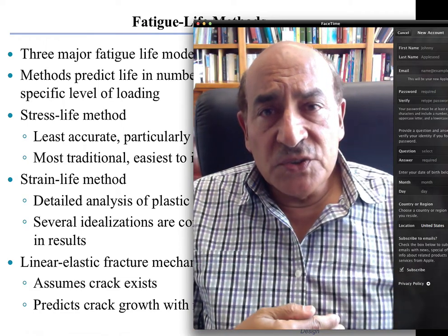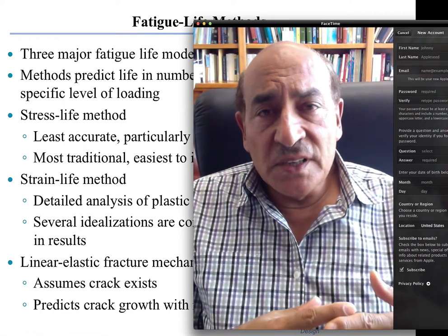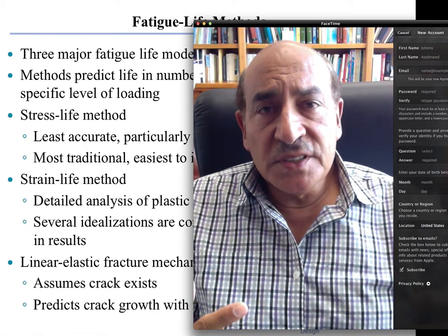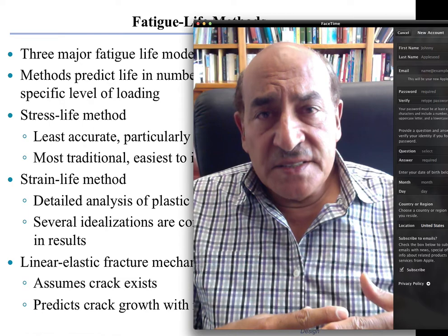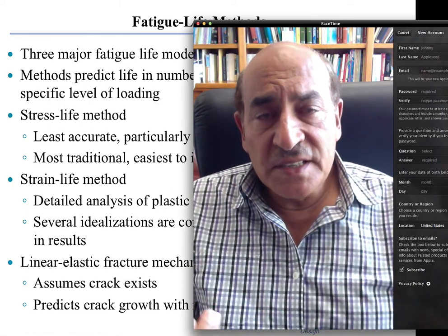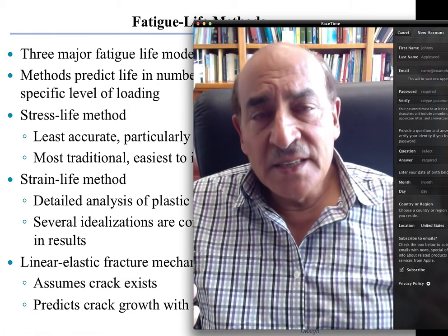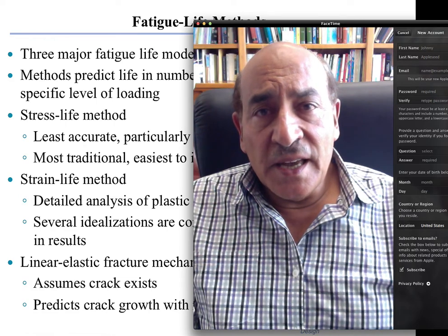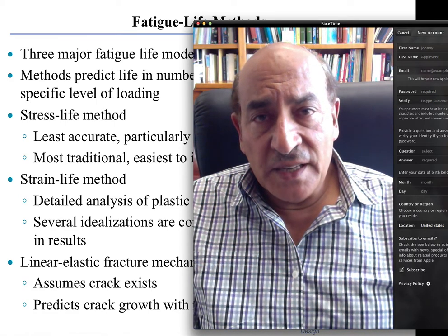So the ultimate way that the crack is going to proceed is by exceeding a certain limit. If it is ductile, for example, it can exceed the yield strength of the material, and the material starts to deform plastically in the remaining section, and then it will rip apart and lead to gross failure.